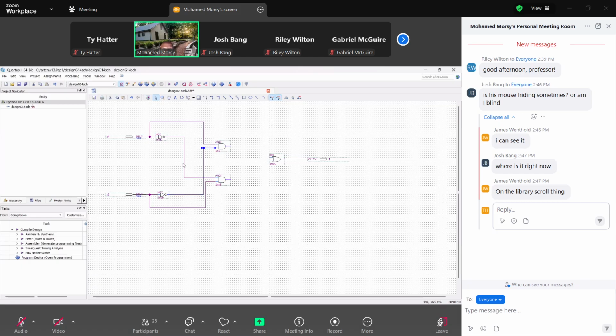In Multisim, oops, we have a bad connection here, so delete it. In Multisim, you can take the wire and go through the circuit. It's different, you can double check. So here you have to take it piece by piece.